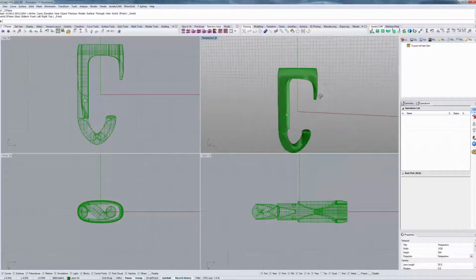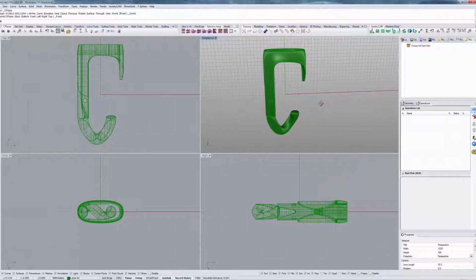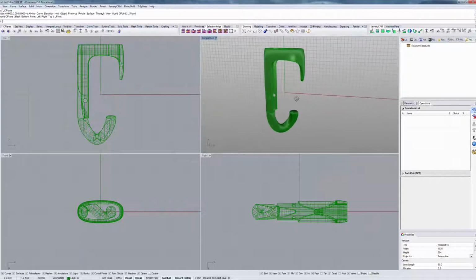And the other issue with this approach is that it really was meant for older mills that relied on either 4 axes, meaning that you have your 3 directions of movement and then a lathe, or alternatively 4+1, meaning 1 manual tilting axis that you would adjust by hand between operations. Now that we have true 5-axis mills that can move all of their 5 axes at the same time, we are able to utilize a new type of strategy called continuous 5-axis milling.